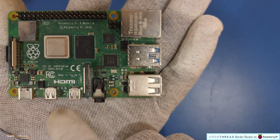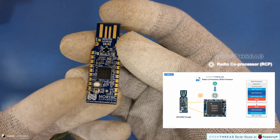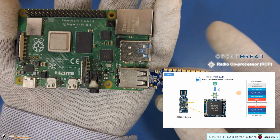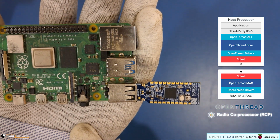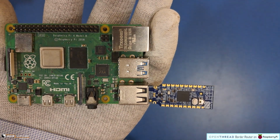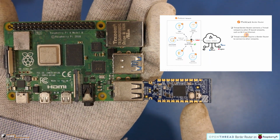On the other hand, the OpenThread radio coprocessor is a physical radio, typically a USB dongle, that provides the actual 802.15.4 wireless communication. It handles the low-level radio transmissions, transmitting and receiving Thread packets under the command of the software on a Raspberry Pi, and is essential for the physical existence of the Thread network itself. A Thread radio coprocessor is needed for OTBR to talk to the Thread network.